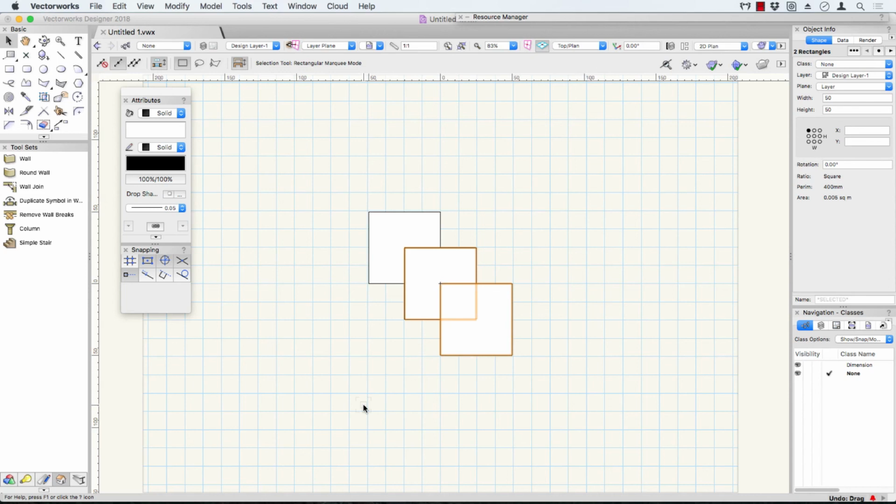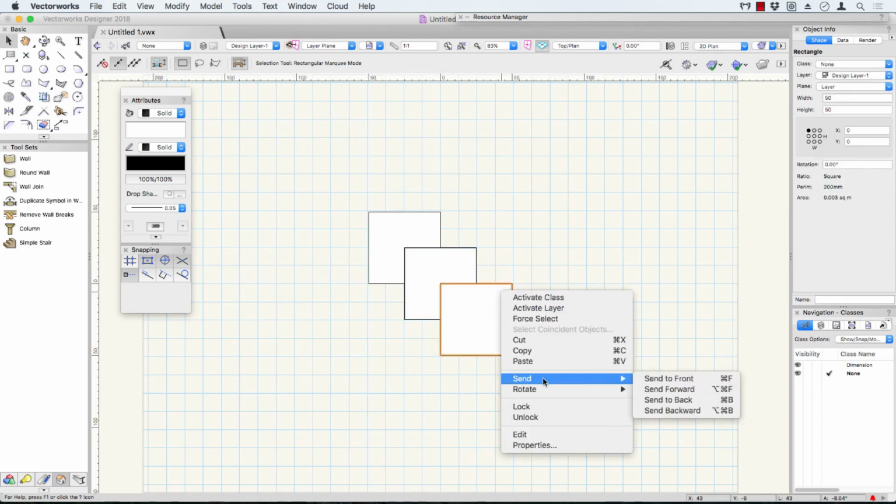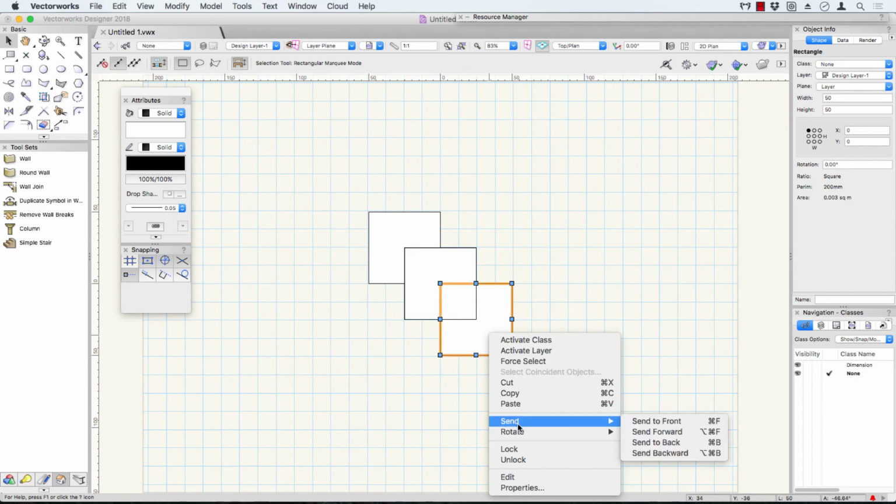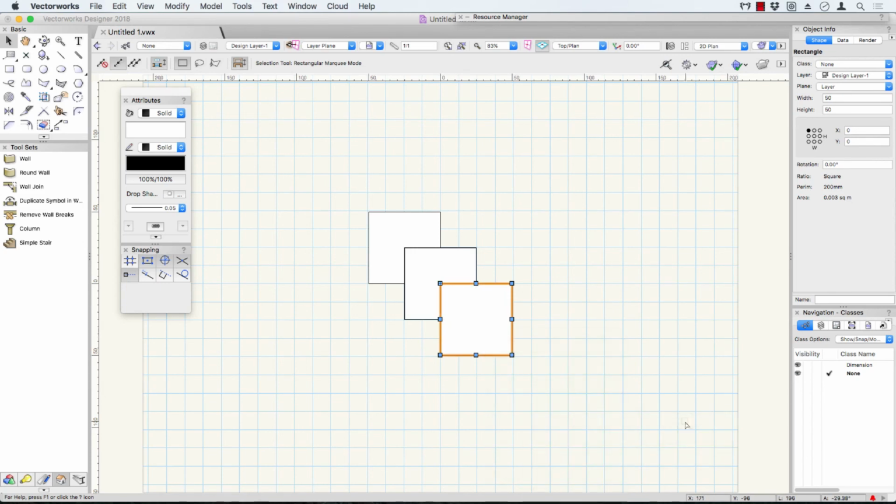So there's something in Vectorworks called the stacking order. So when we have an object in Vectorworks, we can right click on that and we can send forward, back, or send to the back, and that puts that rectangle at the bottom of everything. Right click on it again, send to front, brings it to the front of absolutely everything. Send backward and send forward will move that object one object in the stacking order. And when there's only 3, it doesn't matter so much. But if there was 100 objects, you could do an awful lot of send backward, send backward, send backward to get what you want.